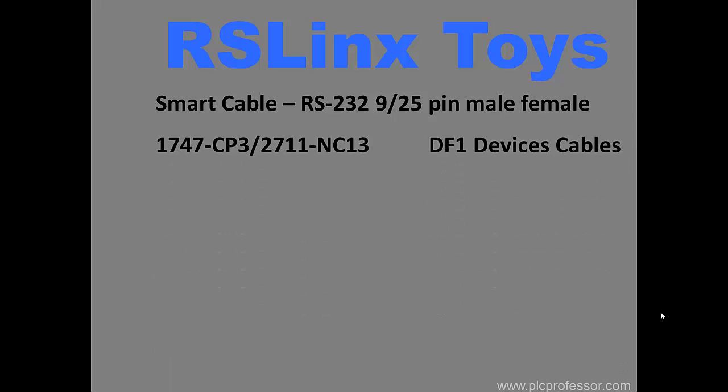Then there's the 1747 CP3 and the NC13 2711. 2711, that's the prefix for PanelViews. 1747, that's SLC 500. And then you have 1784, which is the prefix for PCMCIA adapters.